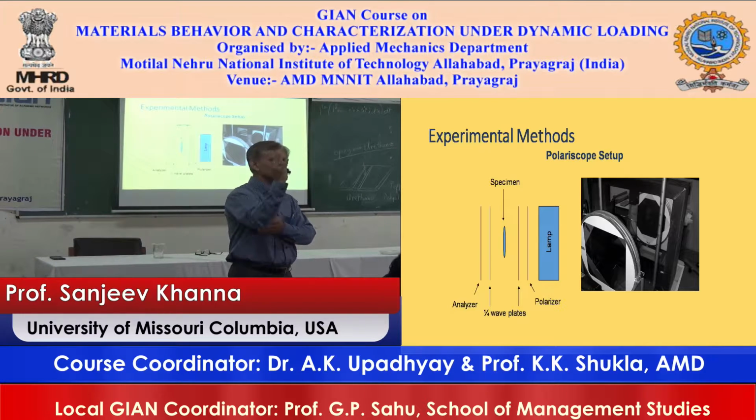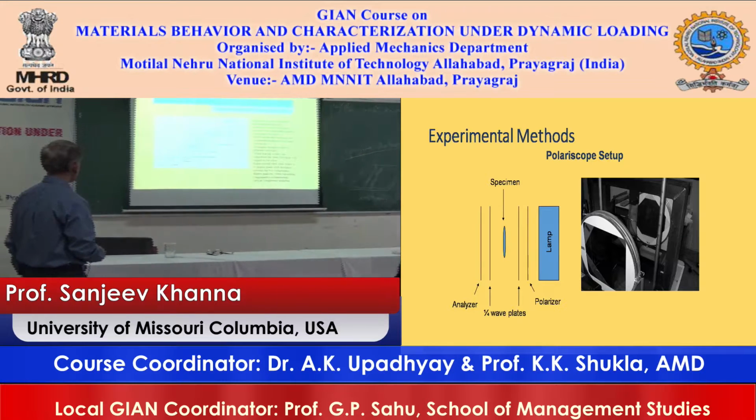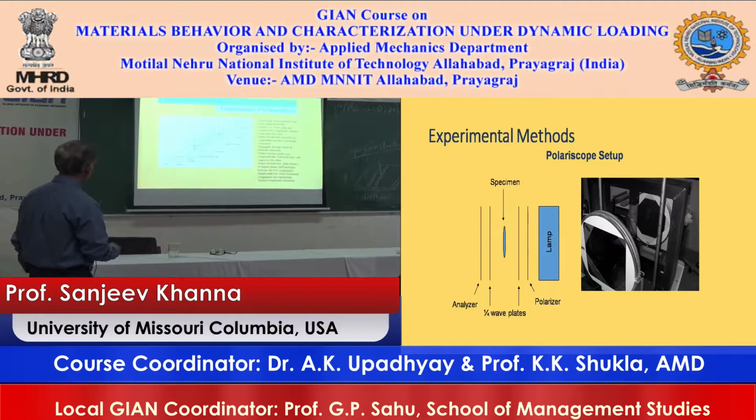When you keep it in the same phase, it's called a bright setup. If you put it on this side, it's a dark setup, so the light coming out is reduced. Both are okay; you can use one or the other. This just shows you the same scheme I talked about, and at any point you have sigma 1, sigma 2 as your principal stresses at that point. So every point is affected like this.